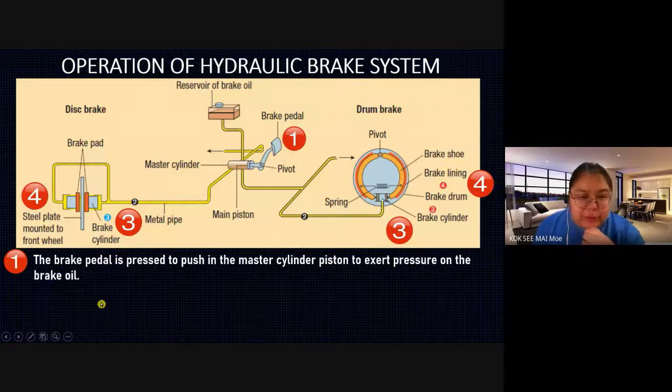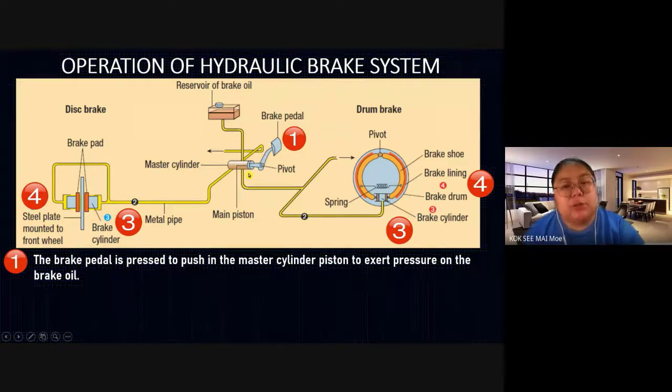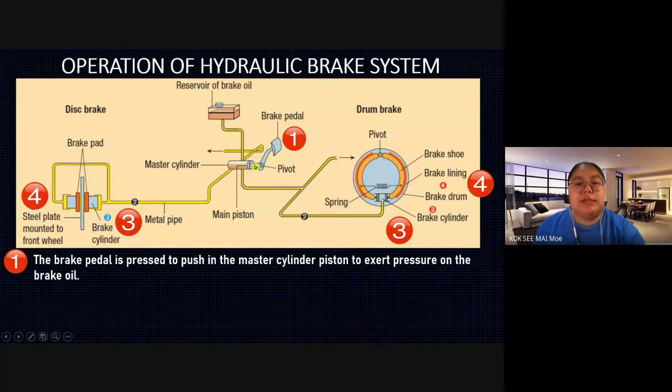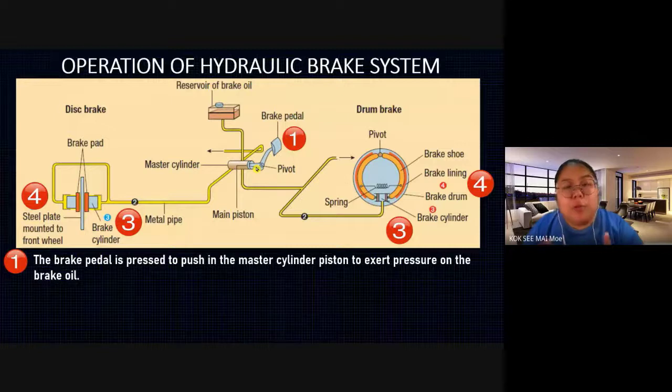Okay, we go to the first one. The brake pedal is pressed and pushes in the master cylinder. This is the master cylinder. So it exerts pressure on the brake oil. So the first step, you exert the pressure on the brake oil. This master cylinder is a very small cylinder. Then the output one is a big cylinder because you want to produce bigger force.